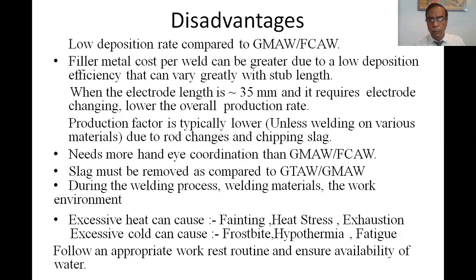GMAW and flux core arc welding are semi-automatic welding, so more production is there, high productivity. Slag must be removed, as compared to GTAW or GMAW. During the welding process, consider the welding material and the work environment.